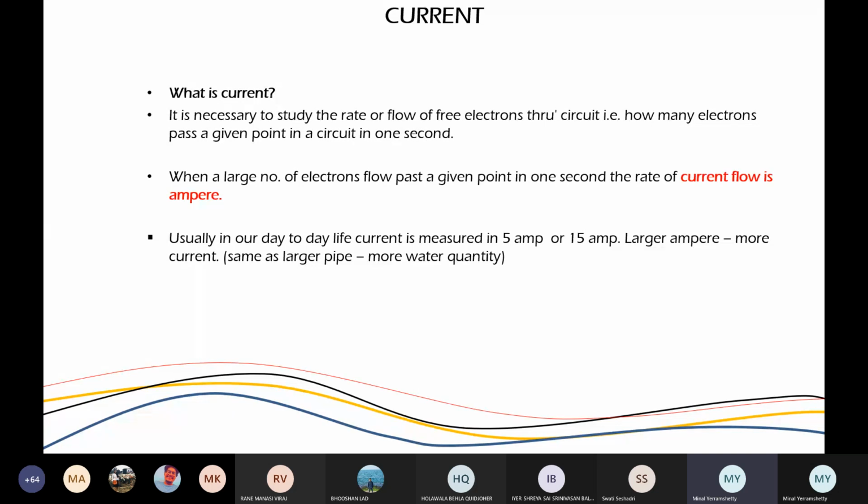So that's why sometimes you will see in your own building, there is no electricity in your house, but in the lobby outside there is electricity. That means the phase on which your house is built has gone out, but the other phase is still working. Okay, we'll do that in the distribution. But I'm just trying to tell you, do not get confused when somebody asks you which phase the AC runs on. It runs on single phase only, so 3-4 wires will not come to it. But it requires higher ampere.